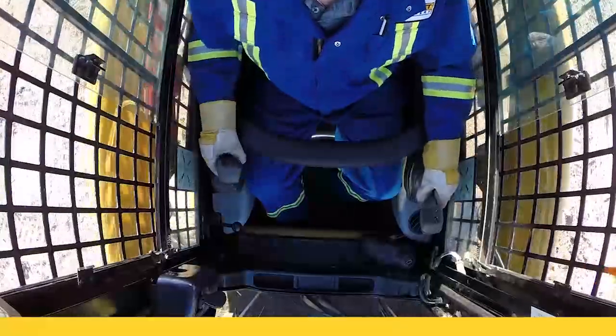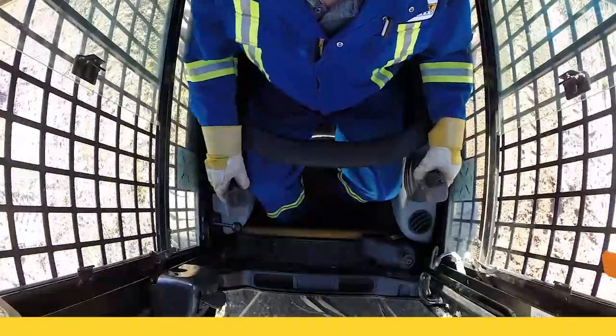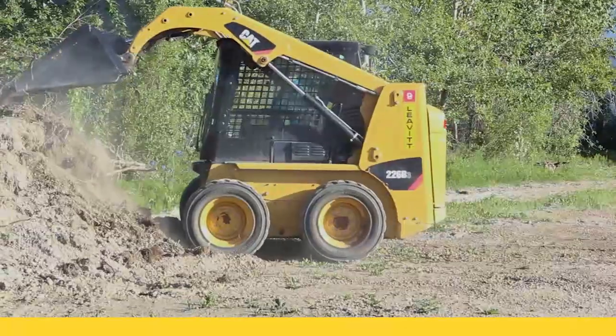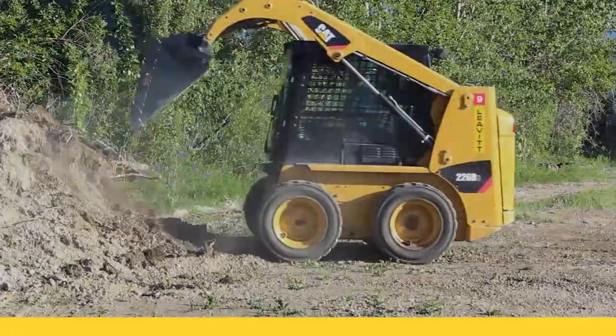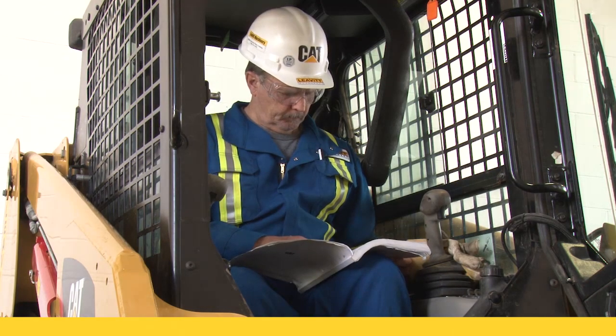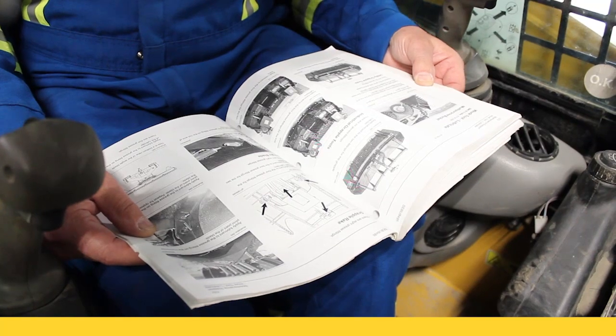Depending on your machine's model, the attachments and other implements may be activated using levers, joysticks, or pedals. Ensure you know how your machine operates before activating your attachments. Note that all skid steer models have slightly different ways of changing attachments. Refer to your operator's manual for the safe and correct way to install your equipment.